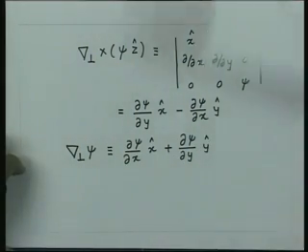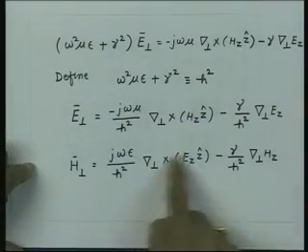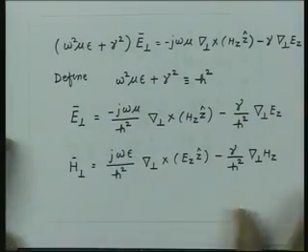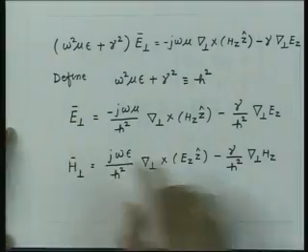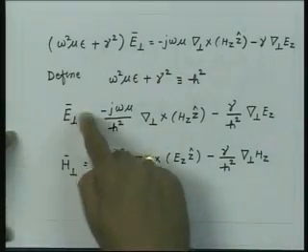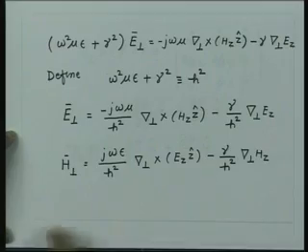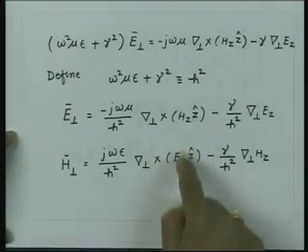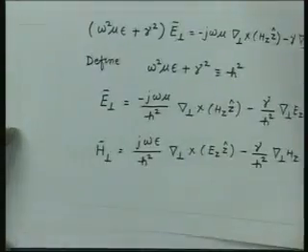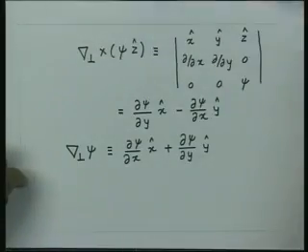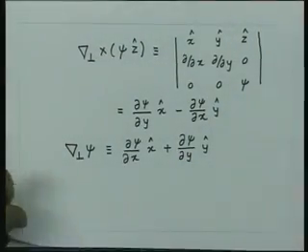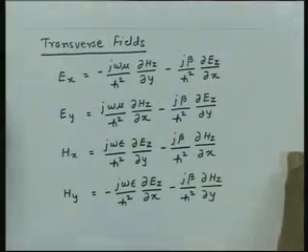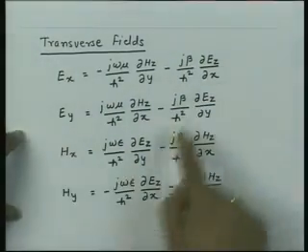So, once you get these quantities explicitly written in terms of the derivatives with respect to x and y, then we can calculate these transverse components Ex, Ey, Hx, Hy in terms of the longitudinal components Ez and Hz. So, in Cartesian coordinates, we can use this expression to get the transverse field components in terms of the longitudinal components, and then the expression essentially would look like that.